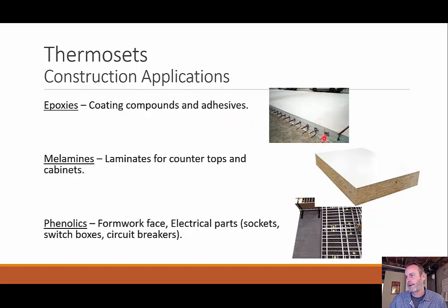Here we see that this rebar, it looks like, is epoxied into this slab. Say you had a slab and you wanted an expansion on it and you didn't have any embeds, you could drill into the side of the slab, squirt some epoxy in there, which is in a semi-liquidy state, put in your rebar, and then it sets solid, creating a very strong connection, and you could build off of that.